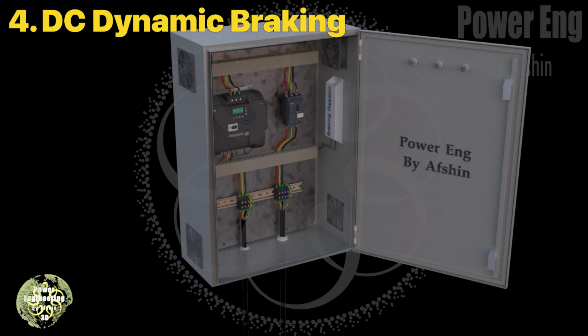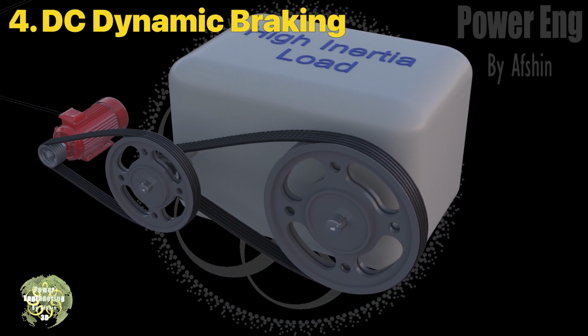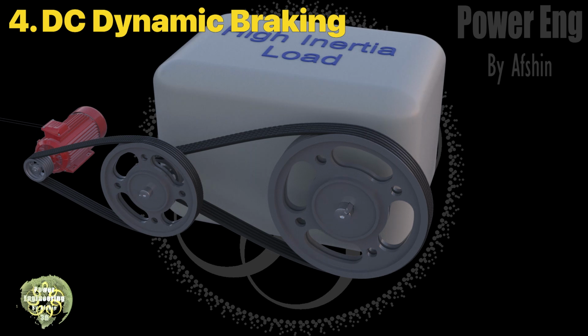Fourth method: DC dynamic brake. This method requires the use of a braking resistor. Additionally, some VFDs do not support this type of braking. In some cases, a braking control unit must be installed along with the braking resistor. The resistor dissipates the energy extracted from the mechanical load by the induction motor during stopping.